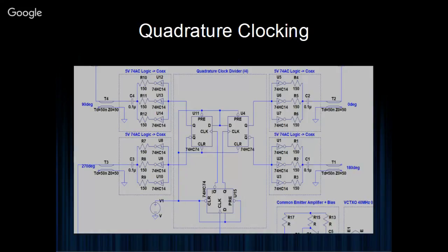So what you can actually do is parallel the gates in such a way that they don't short into each other or into a load, but they share the source or sink current load. And you do this by paralleling the resistor combined with the gate. By paralleling the 350 ohm resistors, you end up with 50 ohms effective resistance. And then each gate is driving around 33 milliamps, which is well under the specified limits.